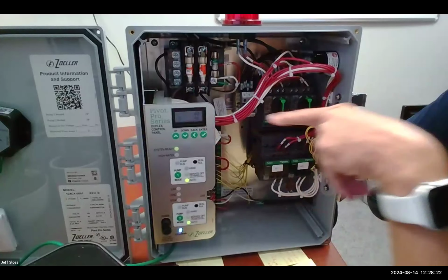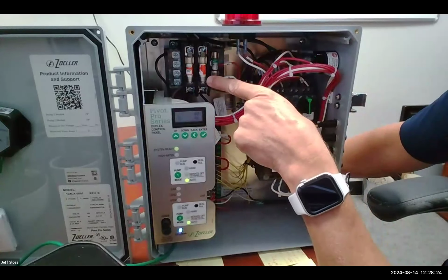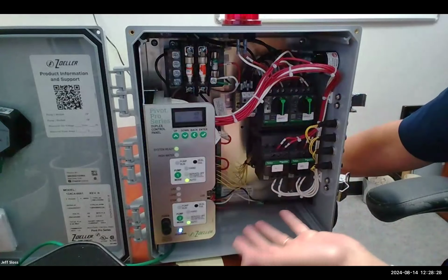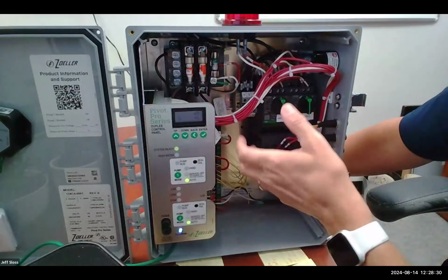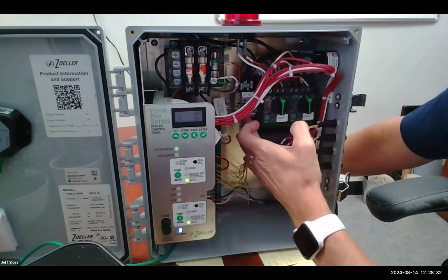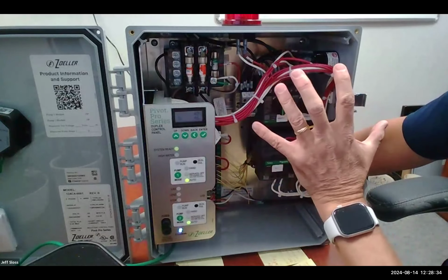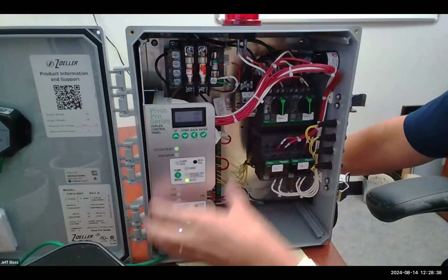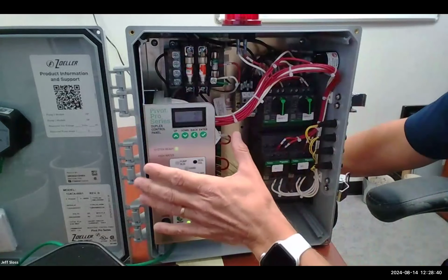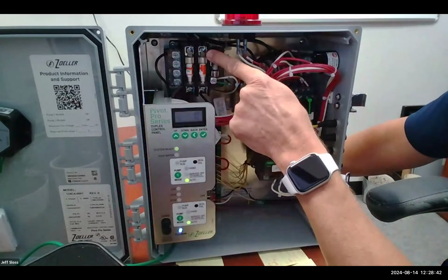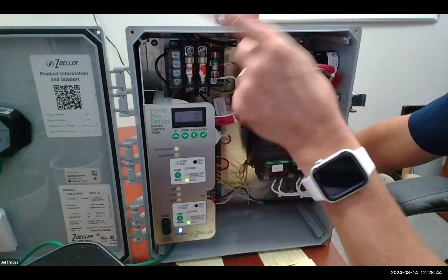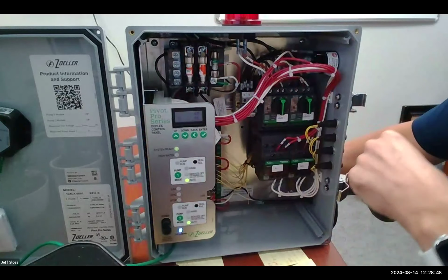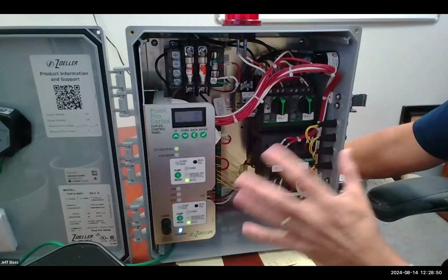And then the other thing I'll point out is why we have a transformer. If you're bringing in 3-phase power right here, which I'm not, obviously, I've just got it plugged in for demo purposes. But if I'm bringing in 3-phase power right here to run my pumps, 3-phase power can't run my electronics and my globe and everything. I need single-phase power for that. That's what the transformer does. This transformer makes single-phase power, 115 volt power for my electronics. That's all it's for.